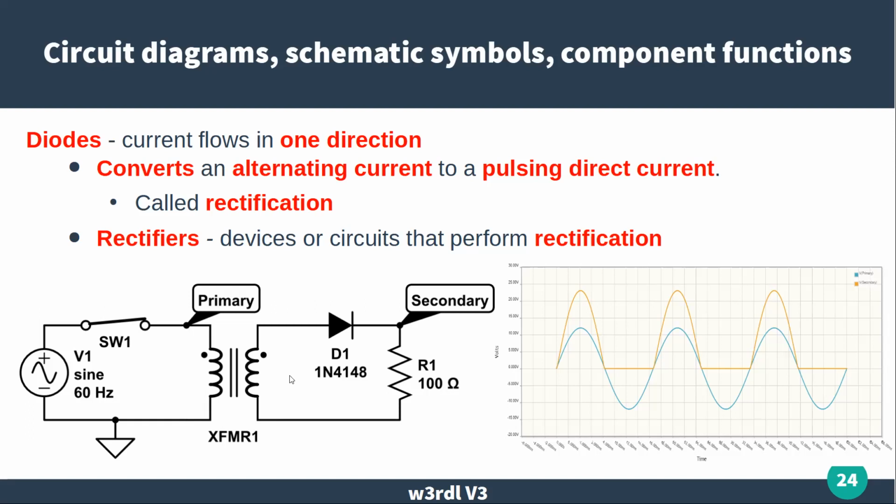So we've got an AC voltage coming out of the secondary of that transformer. It might be more, it might be less, depending on the turns ratio. And as you can see, in this case, it was like a 2-to-1. So the voltage peaks coming out are twice what's going in. So that's the gold versus the blue.